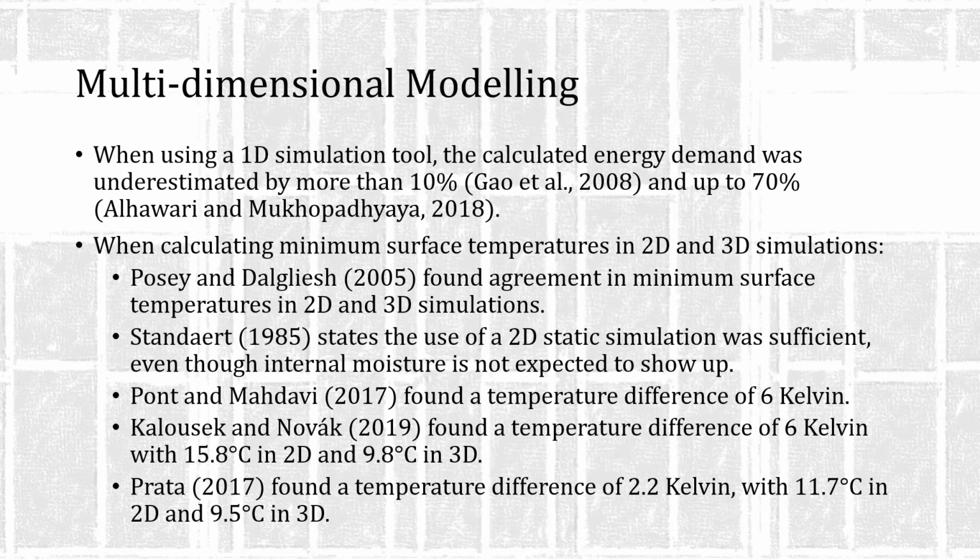Earlier papers written by Posey and Dalgleish and Standard concluded that 2D simulations are sufficient to reliably calculate the surface temperatures, but more recent papers demonstrate the difference between calculated surface temperatures when using 2D and 3D simulation tools. If two-dimensional tools are used, the risk can be overlooked, as the calculated surface temperatures are warmer than what they would be in reality. This suggests the use of the one-dimensional method from clause E3 will overlook the risk of